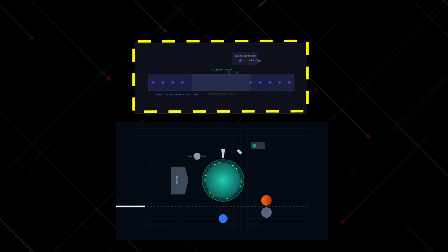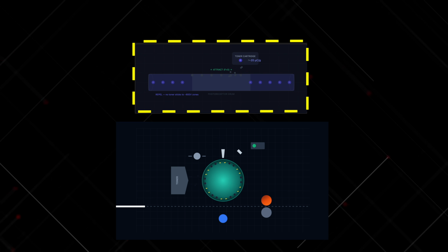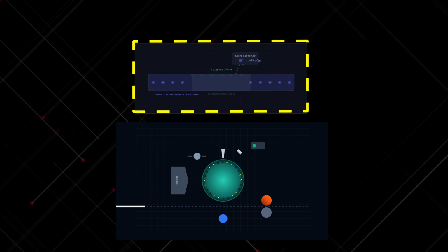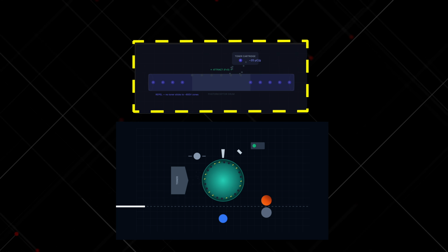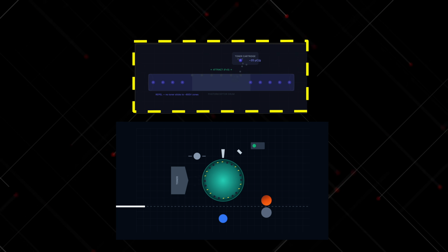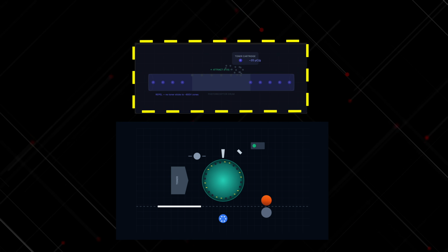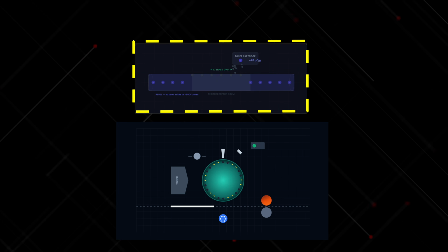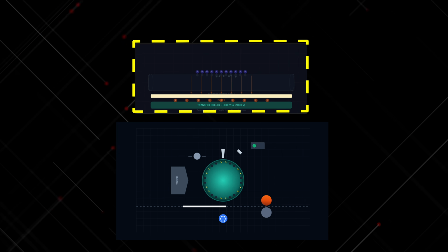So now, when this toner is applied to the drum, then the negatively charged particles of the toner and the drum repel each other. And these toner particles sit on the places of the drum where there is no charge. So basically, they will sit at the places where we want to create the image. So now, once the toner particles set on the drum at the desired location, then the paper is passed between the drum and the roller.